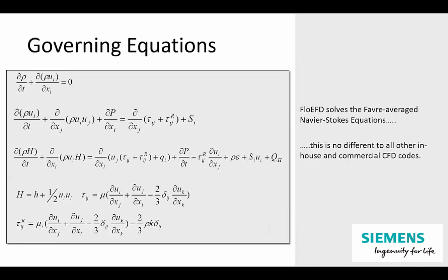Okay, this is the scariest slide in my presentation. These are the Navier-Stokes equations. They're the governing equations of fluid mechanics. Now, to use FlowEFD, it's not essential to understand the mathematics behind these equations. Briefly, they're a statement of three very simple fundamental physical principles: conservation of mass, conservation of momentum, and conservation of energy. The point here is that this is how all CFD works. All CFD works by solving the Navier-Stokes equations. So in this respect, FlowEFD is very similar to other traditional CFD tools.